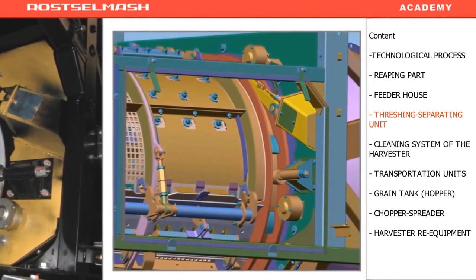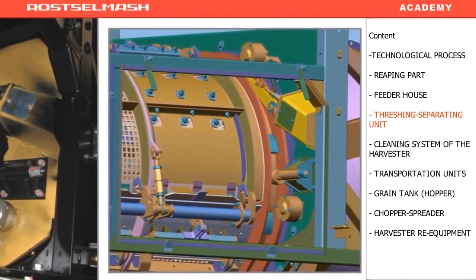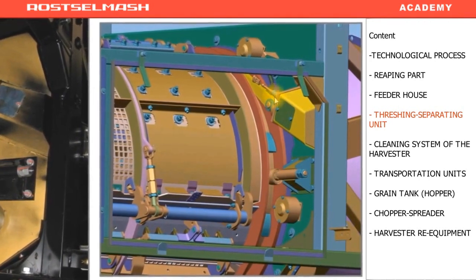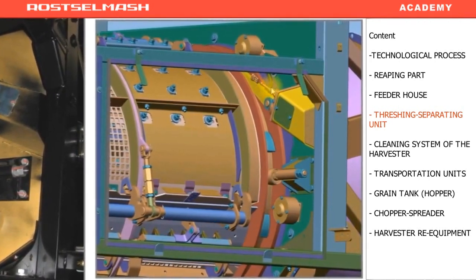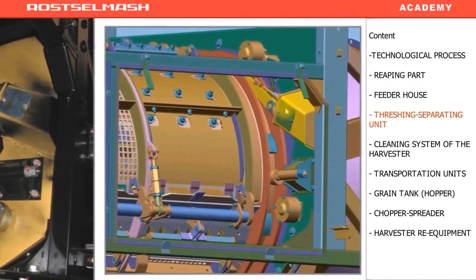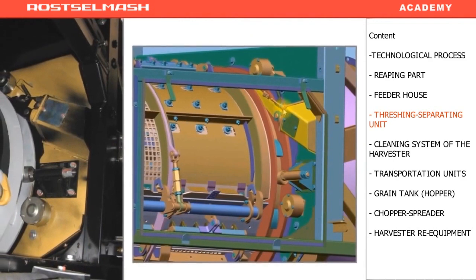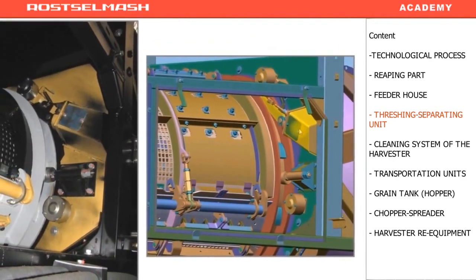For the sensor to work properly and the driver to be notified correctly, loosen the sensor holder and move it all the way in. When it touches the magnet, move it away, move it 2-3 millimeters away, and fix it. In this case, when the lever presses the concave, the lever starts moving away to a distance necessary for the sensor to detect the stopping and notify the driver.